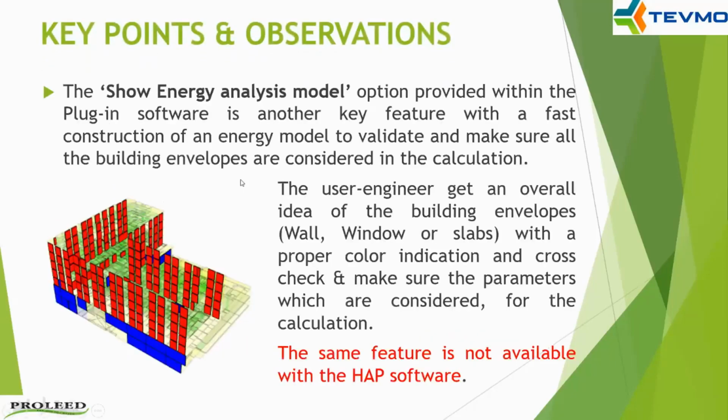Then comes the show energy analysis model option. So this is a very basic feature which is available in Revit also. But what is the advantage is we will be having a fast construction energy model to validate that all the building envelopes we have considered in this project are taken into the calculation or not, because the user engineer gets an overall idea of the building envelopes like walls, windows, slabs with proper color indication, and cross check and make sure that all these parameters are considered.